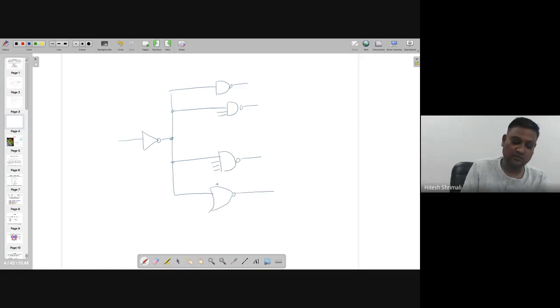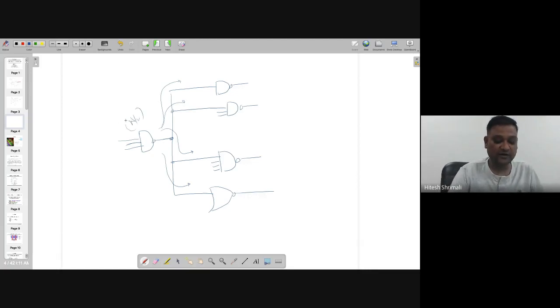So look, this inverter has to drive so many things. Can you see? All the capacitances looking in different directions are going to be in shunt. So then the small inverter cannot do that. Or maybe another gate, let's assume it's just a NAND gate which has 3 inputs. It may also not drive it if you don't make sure of the sizing. So W by L is very important, and for that, we need to find out what W by L can drive the required load.